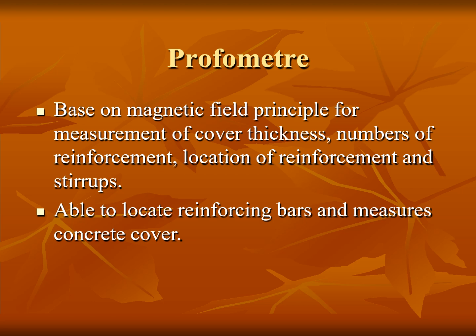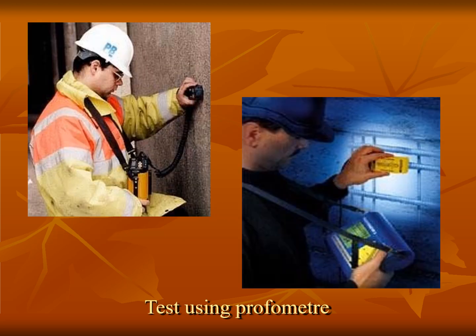Then the profometer. It is used to measure the cover thickness and number of reinforcement bars, and the location of the reinforcement and stirrups. It is able to locate reinforcing bars and measure concrete cover. These are the pictures I show of the profometer testing.